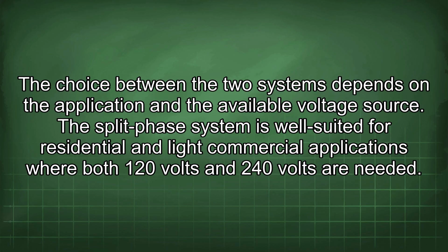The choice between the two systems depends on the application and the available voltage source. The split-phase system is well suited for residential and light commercial applications where both 120 volts and 240 volts are needed.